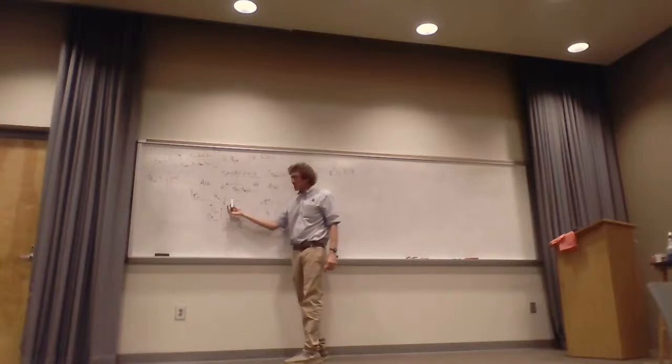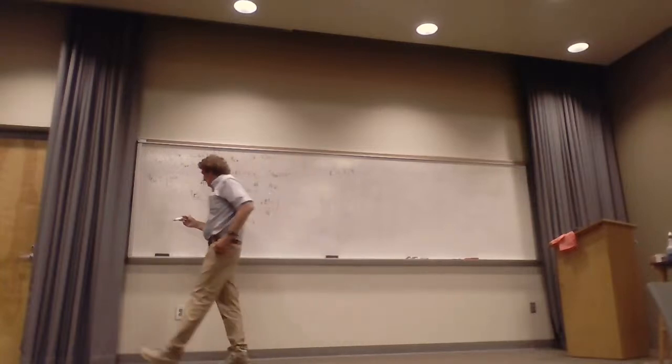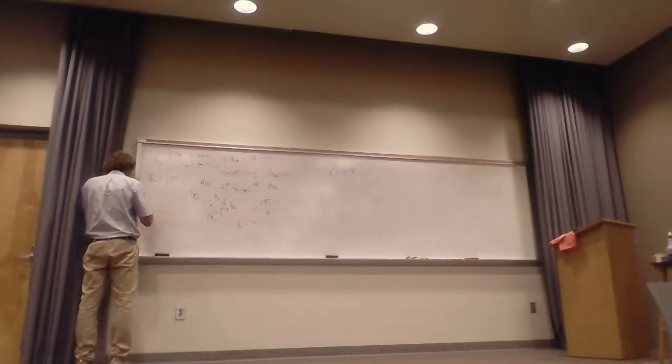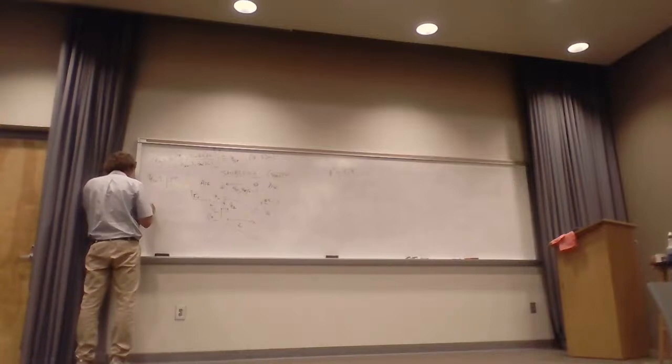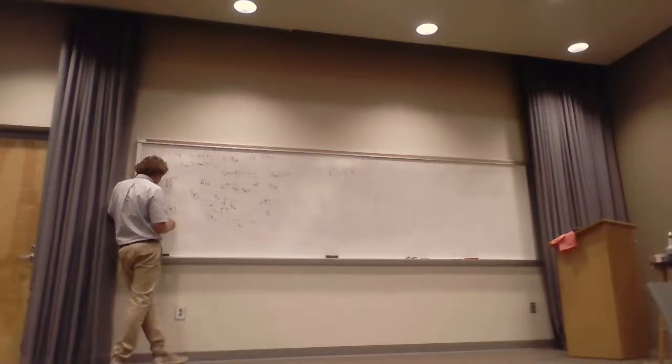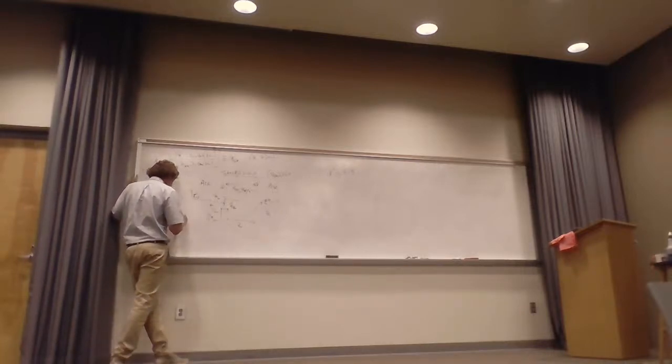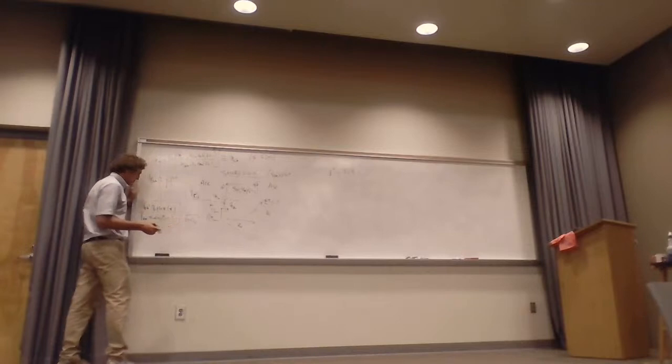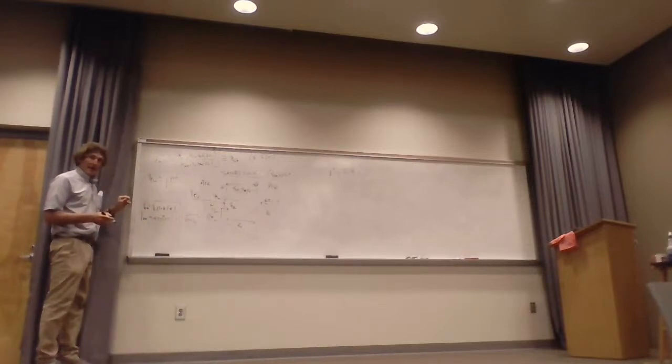Then that electric field is going to start decaying as e to the minus alpha z. So something I can put down here is the propagation constant in the shield, which is the square root of j omega mu. Usually it's sigma plus j omega epsilon, but here I just put sigma. So gamma of the shield is equal to alpha plus j beta, which is 1 plus j times the square root of pi f mu sigma, which is 1 over the skin depth. You remember that? And alpha is equal to beta.